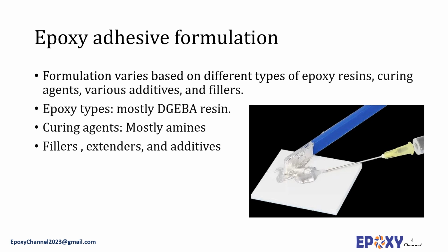Curing agents can be selected based on the nature of the base epoxy resins, application conditions, service temperature, required properties, etc. Although a large number of curing agents has been introduced, here again a limited number of curing agents are employed in epoxy adhesive formulations. The most common ones are amines, including aliphatic, primary and secondary polyamines, tertiary amines, polyamides, heterocyclic amines, and aromatic amines. Aliphatic amines and polyamides are often used in most commercial room temperature epoxy systems, which are to be discussed in the subsequent sections.